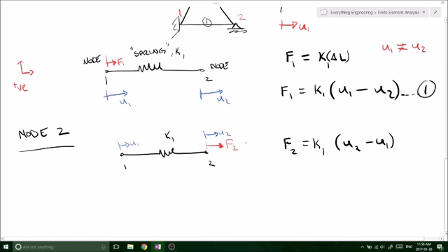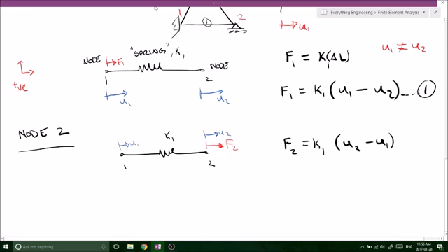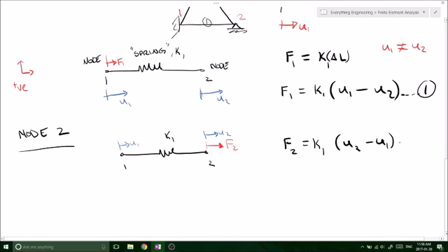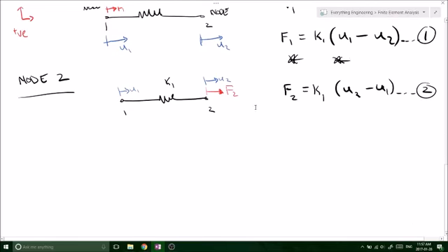This way everything in U2 direction is going to be positive. So by convention, the node that we're analyzing is going to be the one that we want to put first, and this is just how convention and how your teachers will be using it, and it will give us a stiffness matrix that eventually works out in the end with all of our signs. So just know these two formulas. These are important formulas, and this is how a one-dimensional analysis will start, and how you can go by doing your analysis with the matrix method.